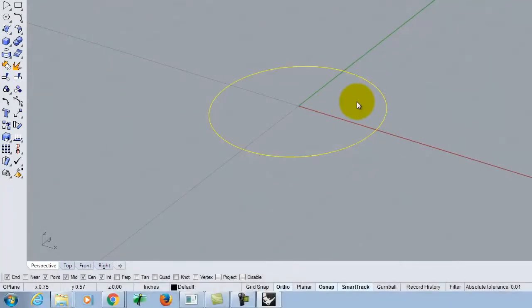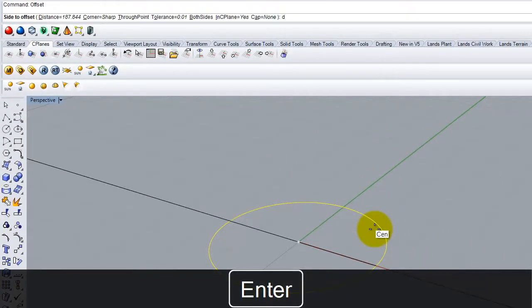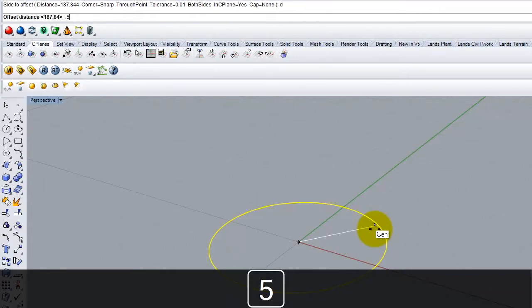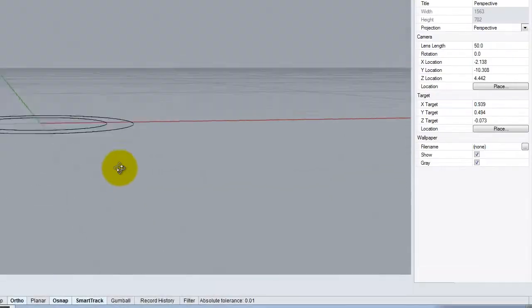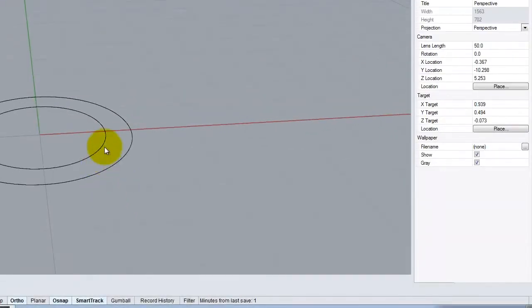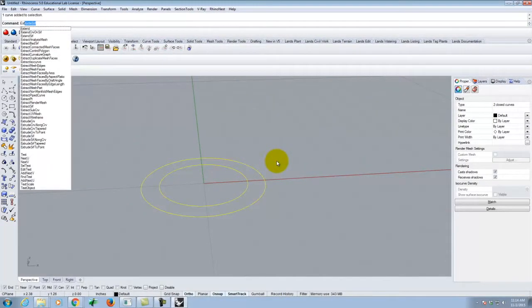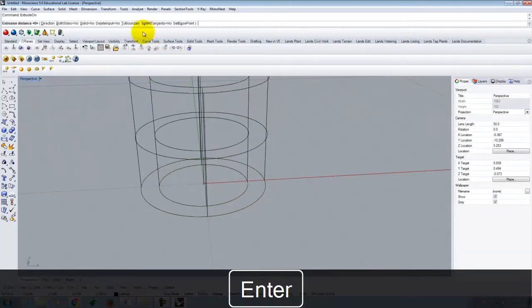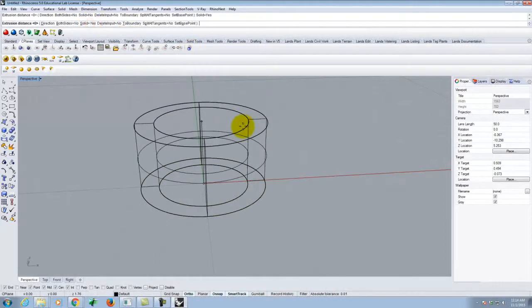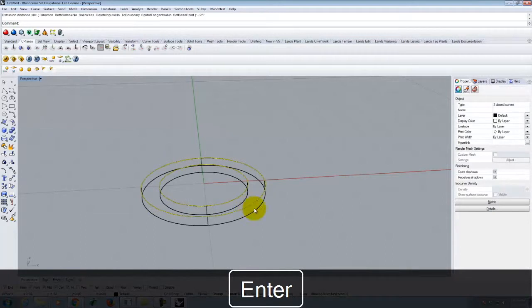I'm going to have a little bit of a trim kit, so I will either offset or do another circle. We'll do an offset with a distance of maybe a 1/2 inch in, something like that. And so you can start to see what this would look like. Let me go ahead and take these two curves, and I can extrude curve. And I want it to be a solid. And we'll extrude it maybe negative 0.25 inches, something like that.